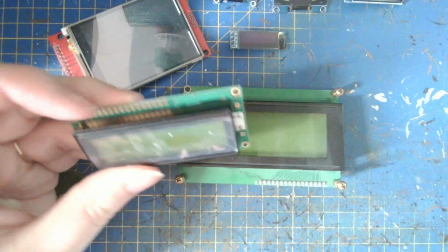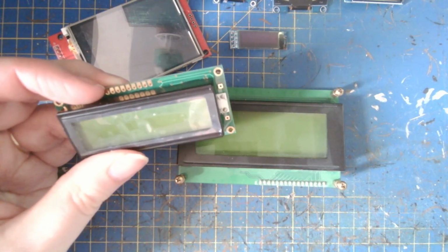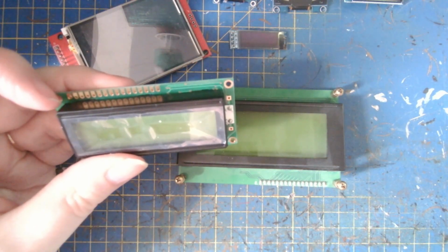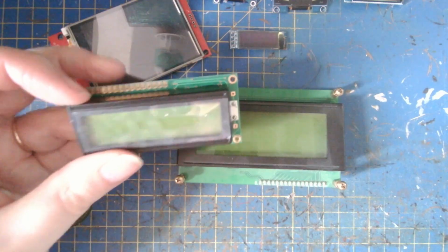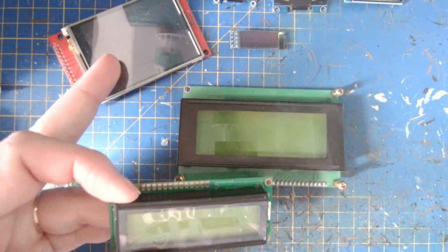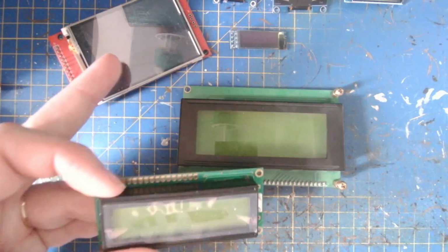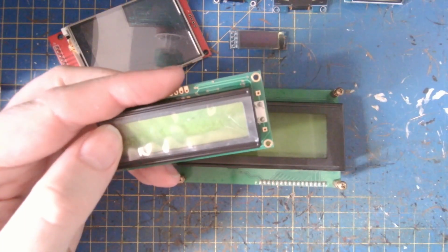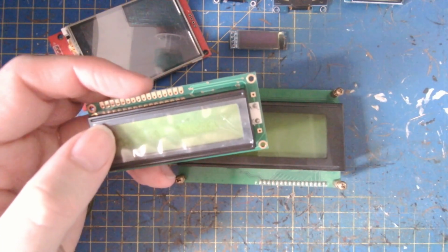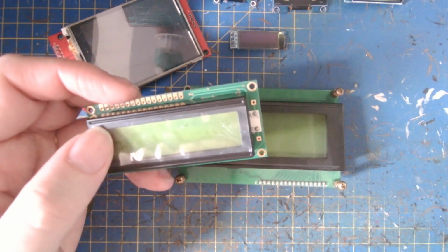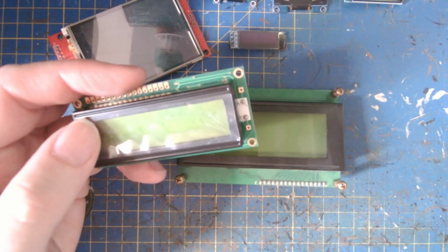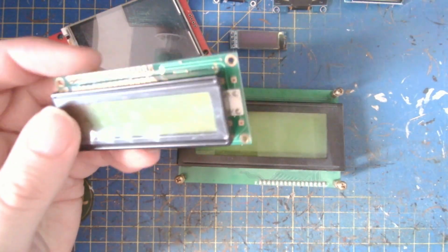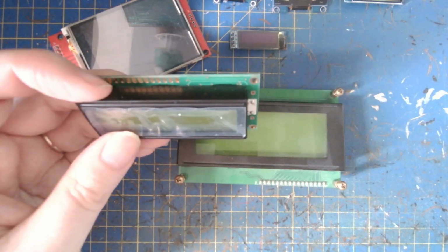Then you have parallel interfaces, and it's called parallel because you're sending multiple bits of data in parallel at the same time. 4, 8 and 16 are the usual ones. There are some 18-bit displays, some of the colour screens. This is actually an 18-bit colour screen. It's just been wired up to use the serial peripheral interface instead of the parallel one. So as I say here, you would have, say, 4 data wires. You will put 0 and 1 on those 4 wires. You will send a clock pulse, and it'll do something with that data. With a serial interface, you have to send the bits one at a time. So the parallel interface tends to be fast, but needs more pins.